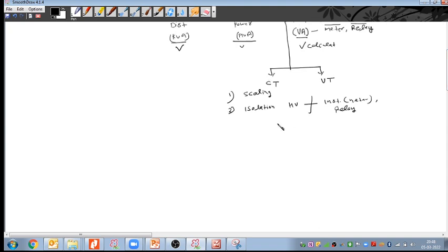Now we have taken the CT, and we started the CT selection and sizing calculations. The current transformer we basically divide into two parts. One is for metering purpose, where we use the current transformer to meter how much current is flowing, and second we use the current transformer for overcurrent at fault, that is the protection purpose. So this metering CT we are now discussing.